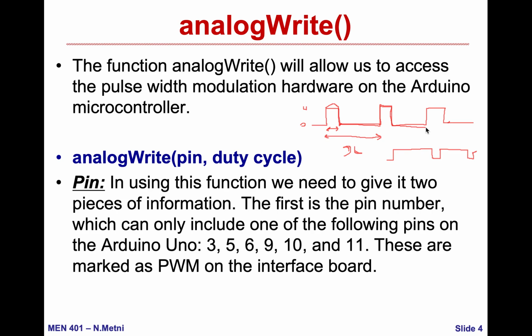The good thing in the Arduino is that most microcontrollers have what we call a PWM engine. So we specify once which PWM we want, on what pin, and what its duty cycle is, and the PWM will start. For this, I will use the analogWrite function. It has two input variables: the pin on which my PWM should output, and the duty cycle that I want.